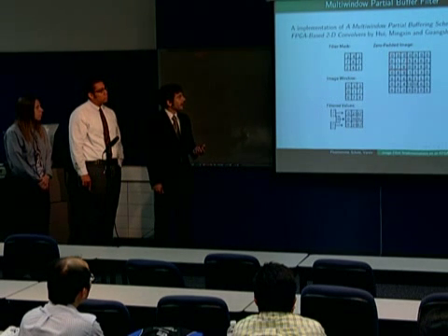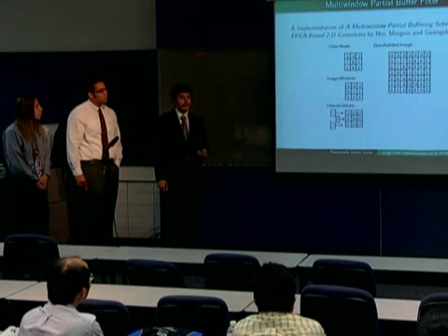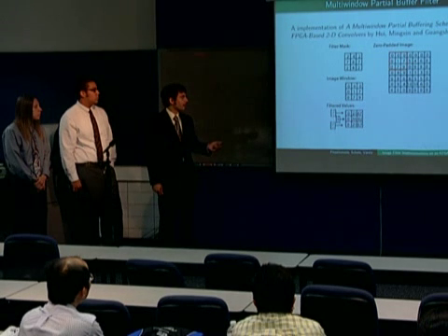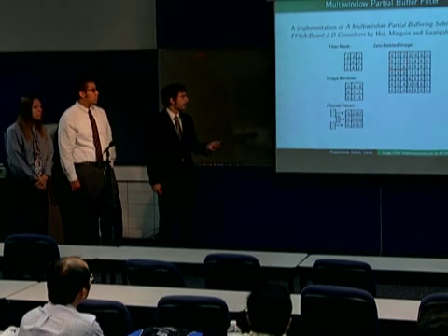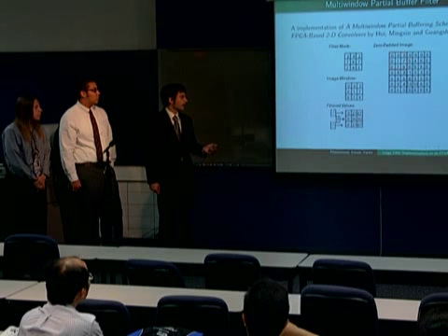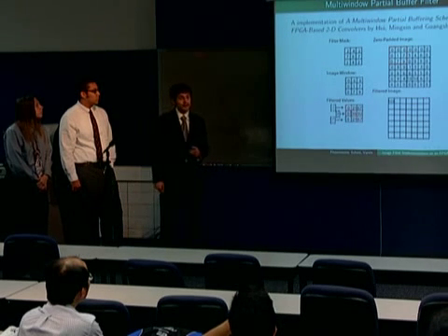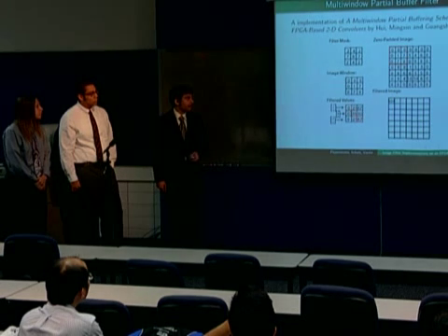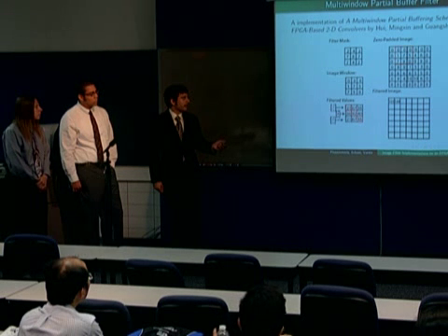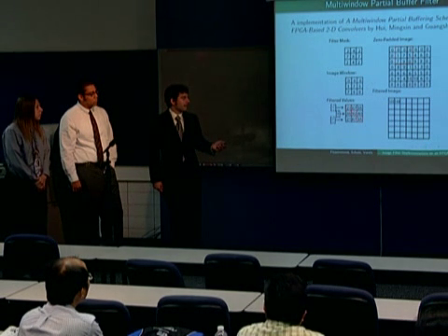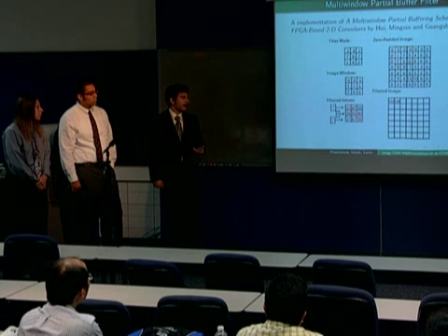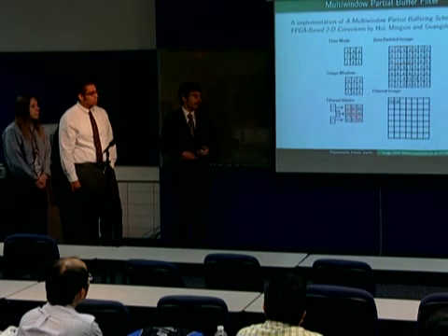And the way I designed this is we have 3 things in memory the size of the image mask. We have the image window, and then the filtered values, each of these rows corresponds to a column in the filter mask. And this is this column applied to that filter, added together, and so on. So then we can take that diagonal, and the sum of that diagonal is a filtered pixel. So then to move this window, we just move all these values in the image window and the filtered values and keep the ones left over. And that allows us to save some time, but we have wasted pixels in this lower triangular. So it's not a perfect algorithm, but it allows for some parallelizability in the future.